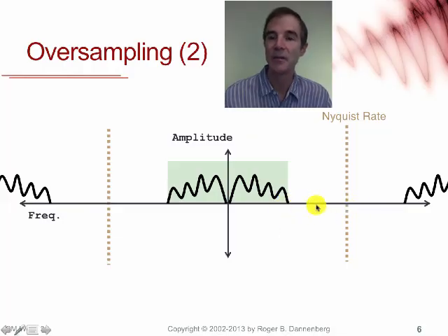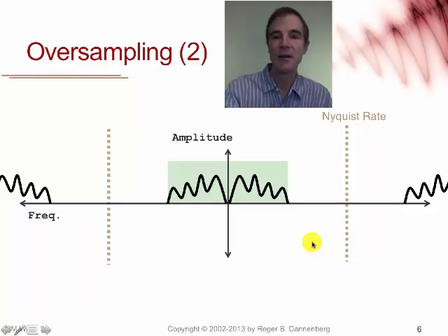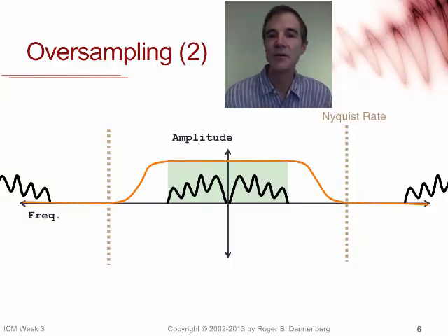Notice that in the digital signal there are no frequency components up in this region. So now when we convert this to analog, we don't have to build a perfect analog filter. We can build one that starts to roll off somewhere above half the Nyquist rate and reaches essentially zero when it reaches the Nyquist rate.